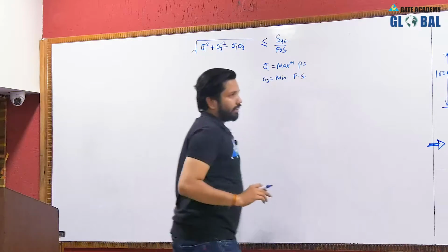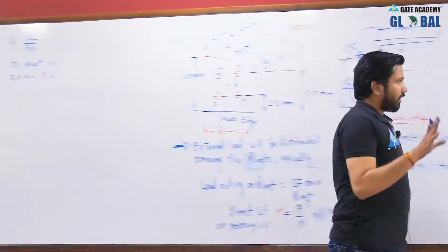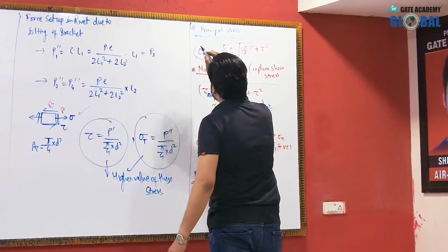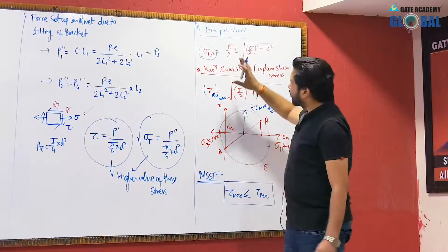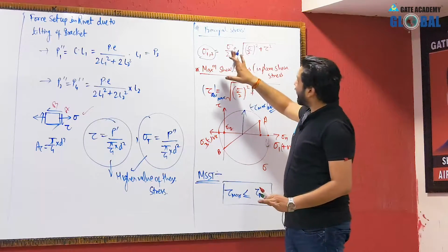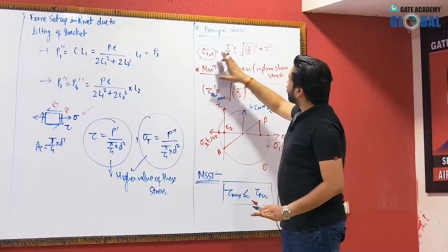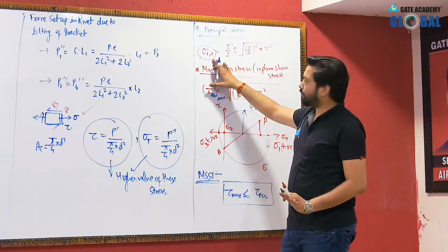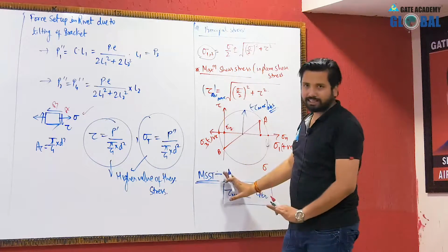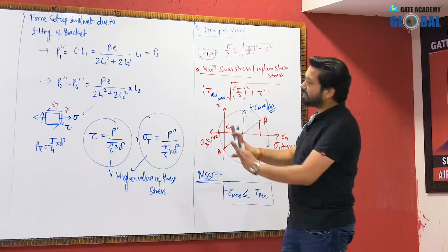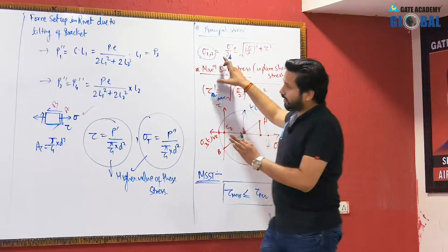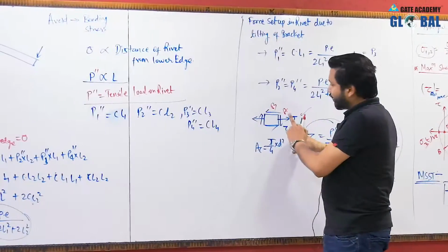If you are confused a little, as here we generally use the formula of principal stress in this form, let me tell you that this will lead you to the maximum and minimum value of principal stress only for this particular case, as this is a case of a plane stress problem, and the normal stress in the state of stress is acting only along one direction.